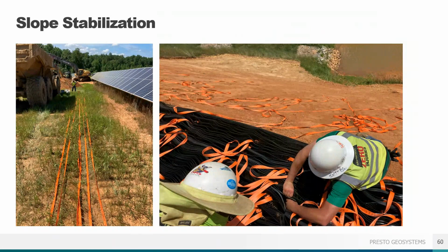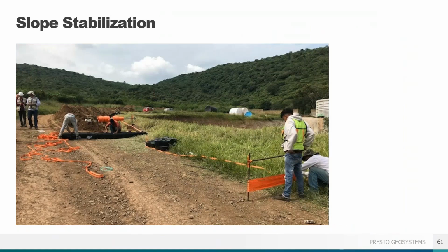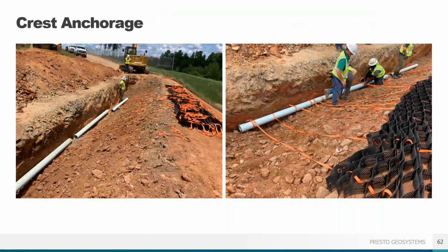Tendons were laid out, measured, and marked per design, then inserted through the eye slots on the slope crest, with sections being built on the flatter ground where it's safer and easier to work. A suspended rod through the tendon spools is a good technique tip that can be helpful when marking and inserting the tendons. For this GEOWEB slope protection system, a PVC pipe was used as a dead man anchor at the crest of the slope, and here's the connection of the tendons to that pipe.